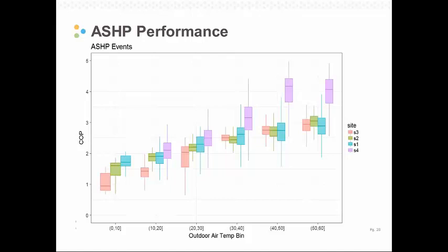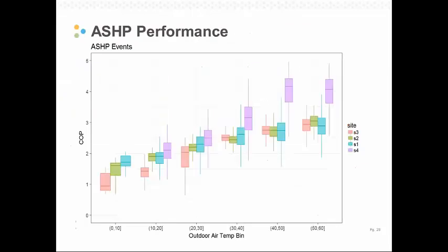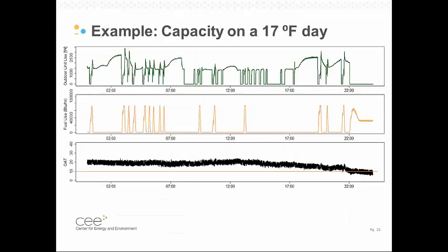These are some really high COP numbers, which really indicate the potential for savings. Everything's really straightforward when the heat pump is on. Things match the conditions. They work great. As I mentioned, though, there's this propane runtime that we need to account for. And that really comes in through two ways: the operation of the equipment at temperatures below that switchover point, as well as the defrost.